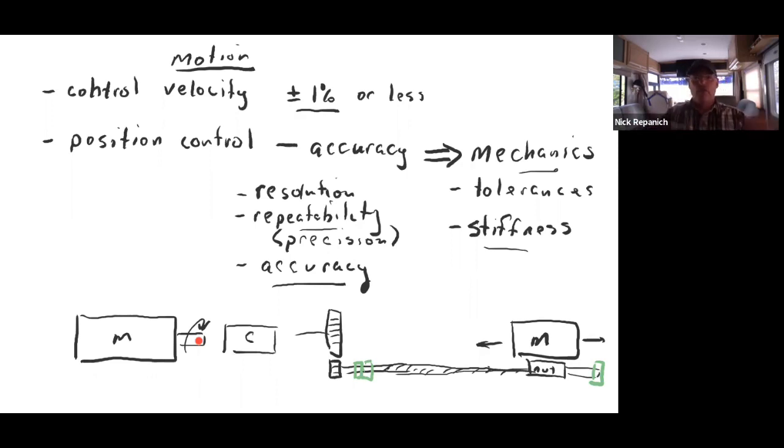But if you went down and bought a 1/4 inch rod at the hardware store that was 3 meters long, and you put a set of vice grips on this end and a set of vice grips on this end, and you twisted, you could easily twist a 1/4 inch rod quite a ways, right? It has a very predictable deflection, depending on the makeup of the steel.